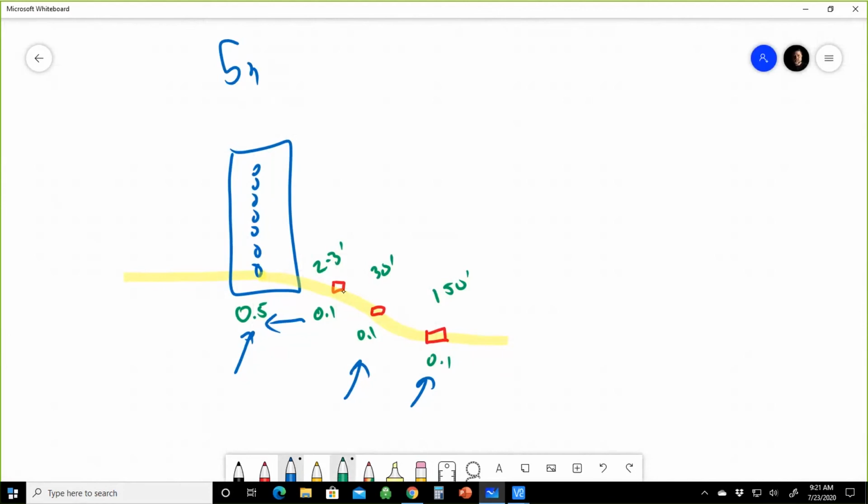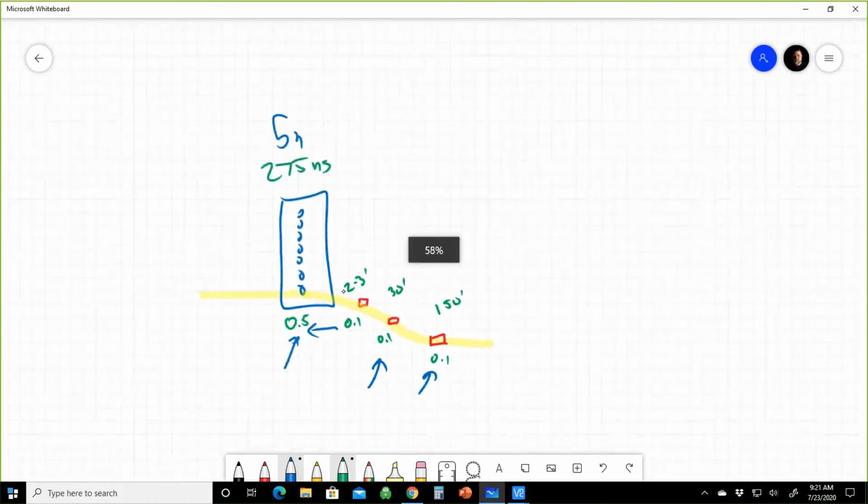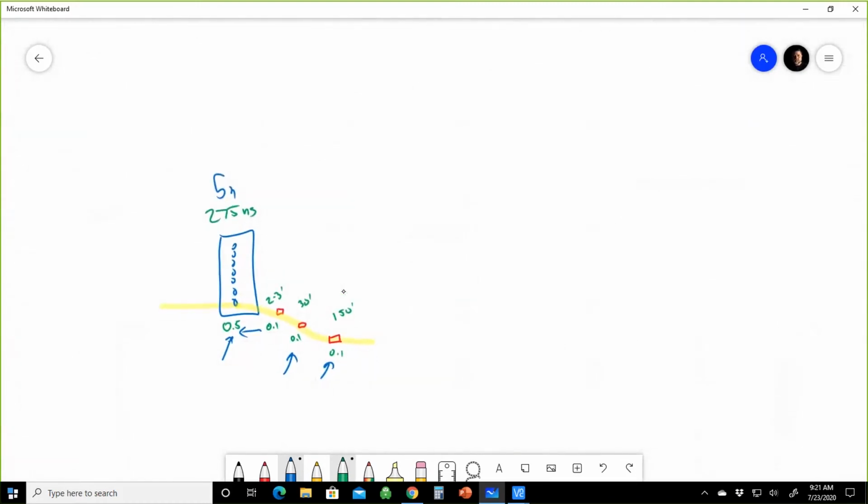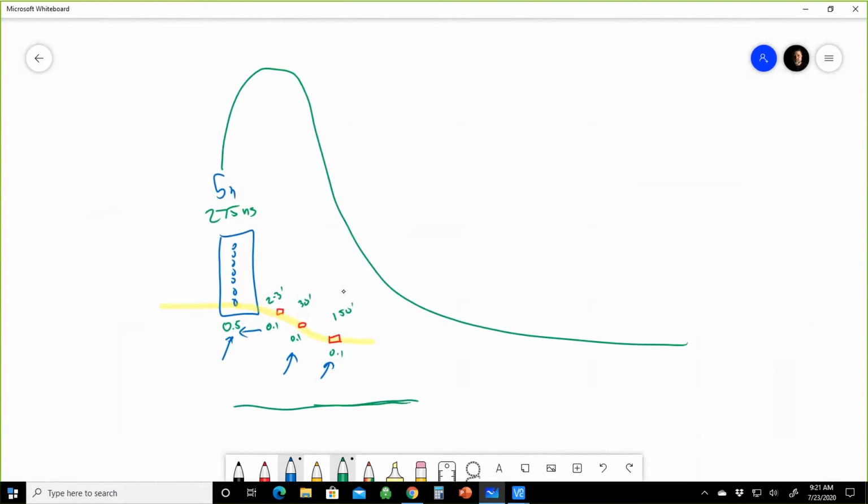Now, if you scoot over to 275 nanoseconds because you're testing further, you're going to have this here on your launch. And so if you zoom into the launch, which we'll do in a second, you're going to hide all of this. All of these losses will get sucked into the connector loss. And so now all of a sudden we're looking at your launch, because of course you have a launch cable here, right? So you're able to measure this connector. And so now you'll have basically 0.8 dB of loss at your connector. And you'll scrub that all day long and it's never going to get below 0.5 because this is merged.